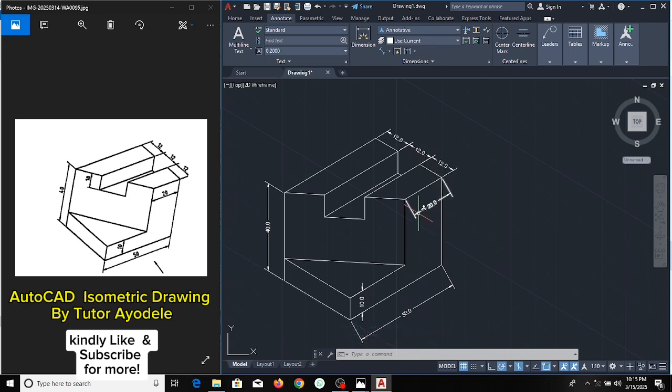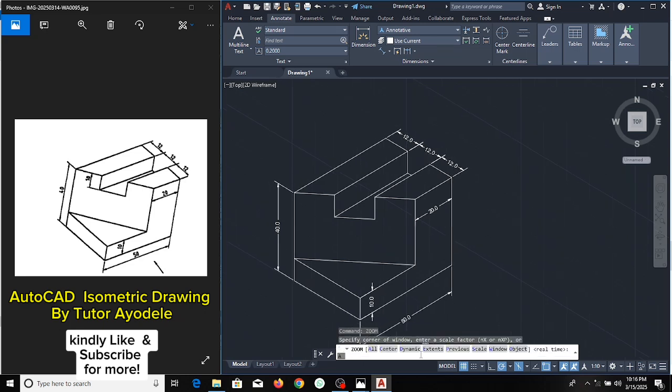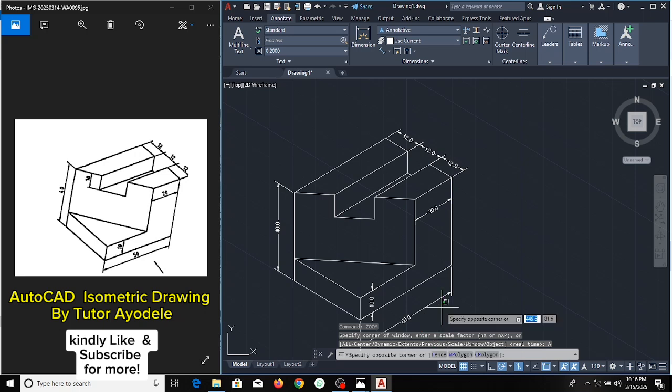And now the last one is the one that is supposed to be in 90 degree, this and this. Okay, so go to dimension, the oblique, and select the dimension you want to align. So you align it to 90 degree, as I said. After pressing enter, 90 degree, then you enter, and here is the outcome. So let's zoom all of it, so you can see that.